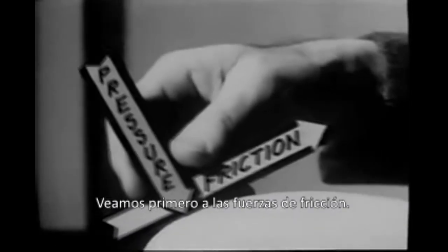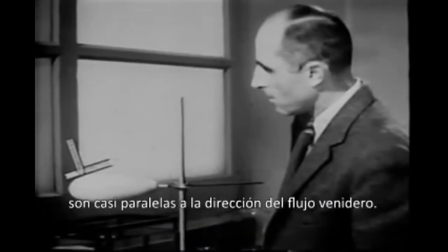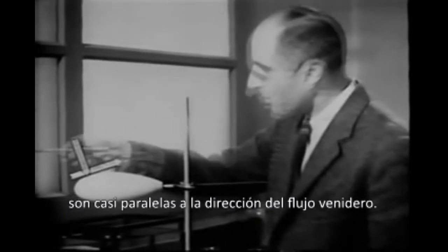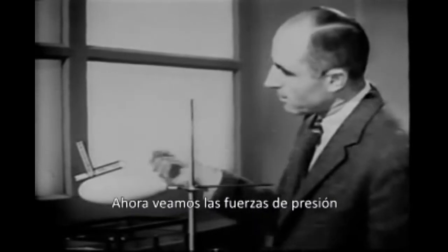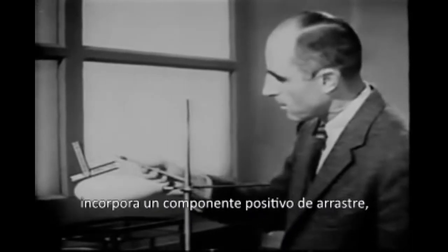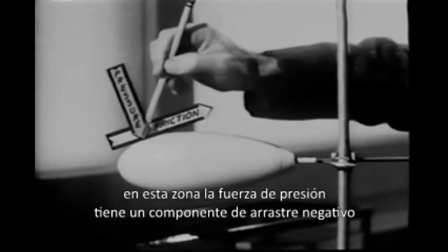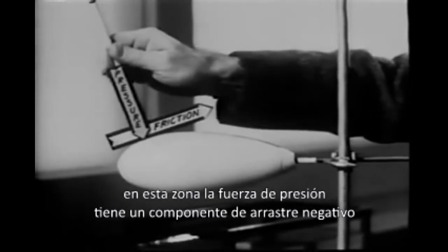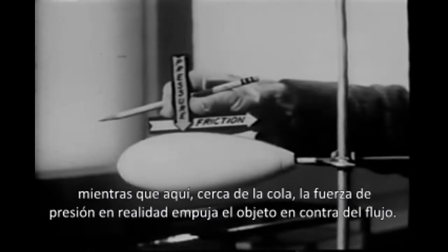Let us look first at the frictional forces. You can see that over most of this body, the tangential forces are nearly parallel to the direction of the oncoming flow. Thus, they contribute considerable frictional drag. Now let's look at the pressure forces. At this point near the nose, the pressure force normal to the surface incorporates a positive drag component. At the shoulder, the pressure force has zero drag component, while here near the tail, the pressure force has negative drag components. That is, the horizontal component of the pressure force actually thrusts the object against the flow.